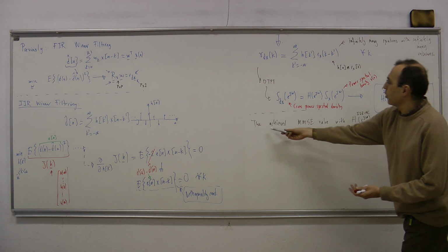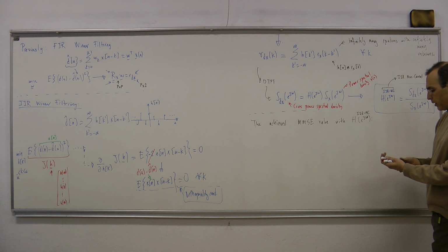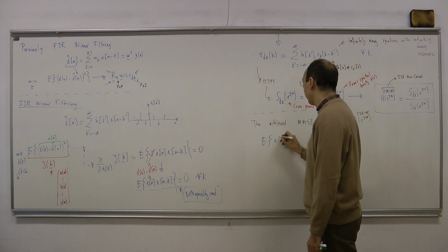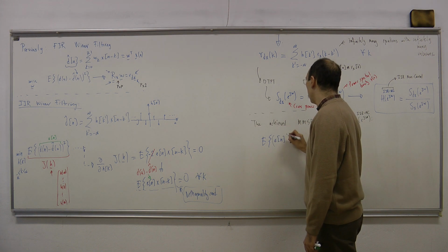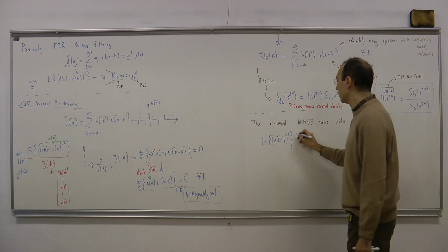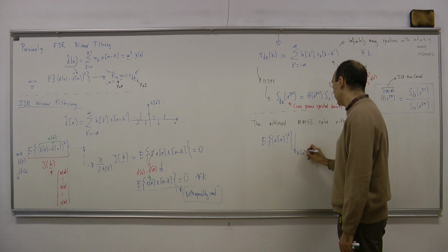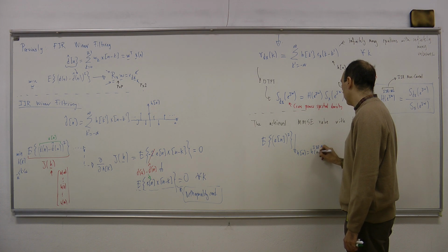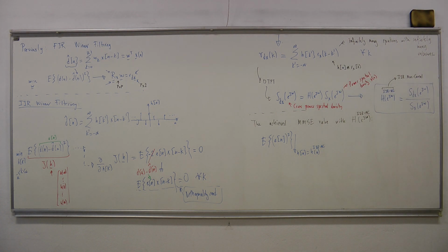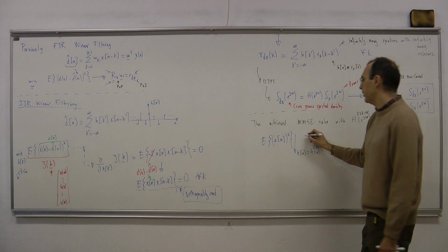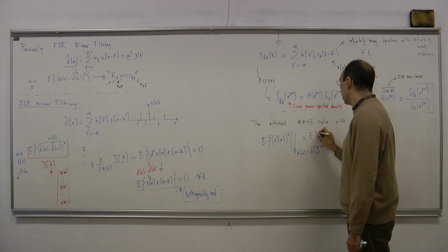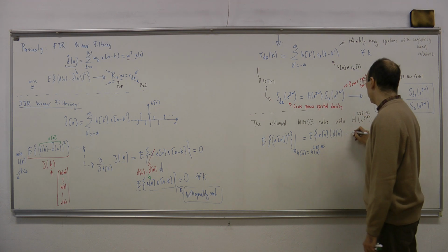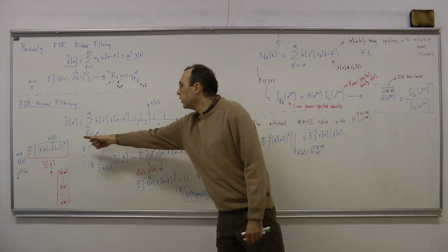Now let me try to calculate this achieved MMSE value. Again, how can I do this? Well, this is E of n squared, with h of n equal to H_IIR non-causal of n. For this, what is the value of this? So this is equal to, as we did before, E of n times d hat of n, because error is this.